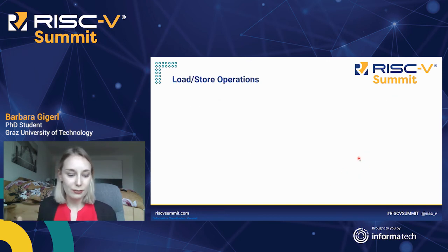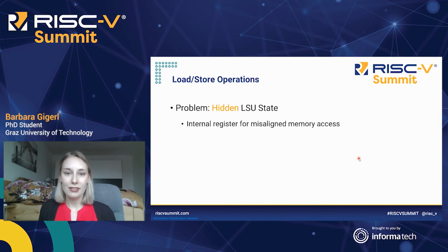And the third source of leakage are the Loadstore operations, to be precise, the misaligned memory accesses, because misaligned memory accesses use a buffer register internally to accumulate the memory word which should be read. This is an internal register in the Loadstore unit.